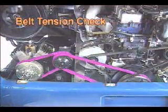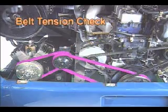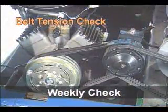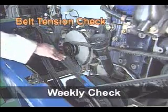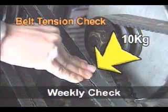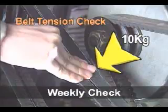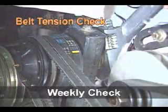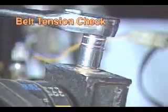Belt tension is also an important maintenance point. Belt tension should be checked every week, and it should be adjusted as follows in case of abnormal condition. Check the amount of deflection when the middle of the compressor or crank pulley and idle pulley is pressed with the force of about 10 kilograms. If the amount of deflection is out of specification, loosen the idle pulley nut and adjust the idle pulley so that the amount of deflection is within specification.